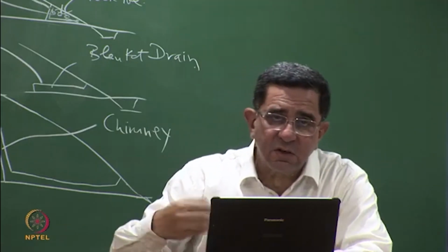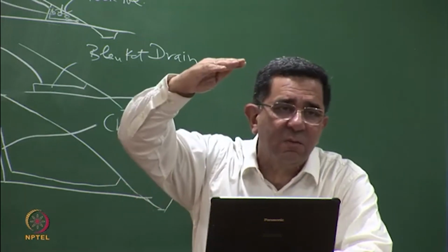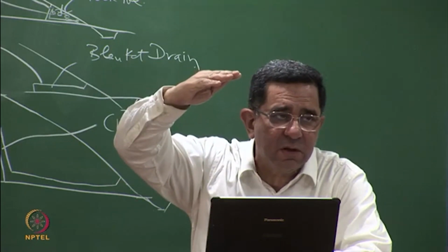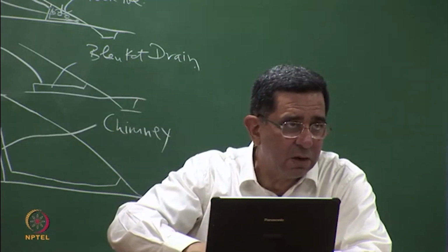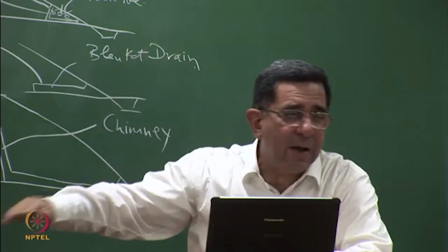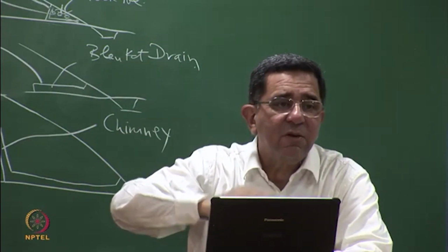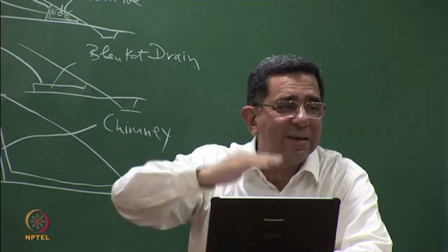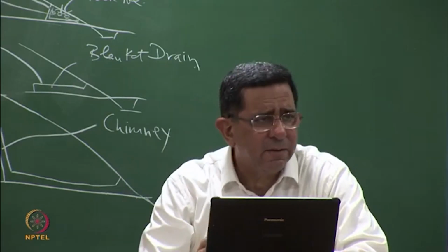In staged construction, the rapid drawdown is for the upstream slope, you remember, and the water is supposed to fall from the highest reservoir full level to the depleted reservoir or the minimum reservoir level. So if you have a 25-meter high embankment, it could fall by 20 meters. But in our case, every 3 or 4 meters, the ash is getting deposited or the tailings are getting deposited, so the upstream slope is getting buried.